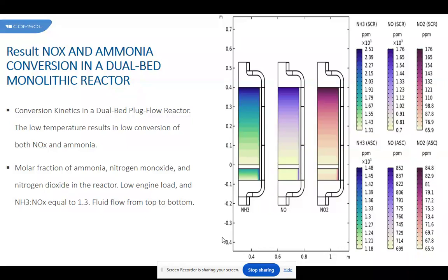The monolith substrate can be made from either metal or extruded ceramics. Here we limit the discussion to the more common ceramic versions. Furthermore, we discuss the straight-through design and not the type used in wall flow filters. This type of substrate has proven to be convenient in many industrial processes such as carbon dioxide hydrogenation, monopropellant thrusters, and pharmaceutical synthesis.